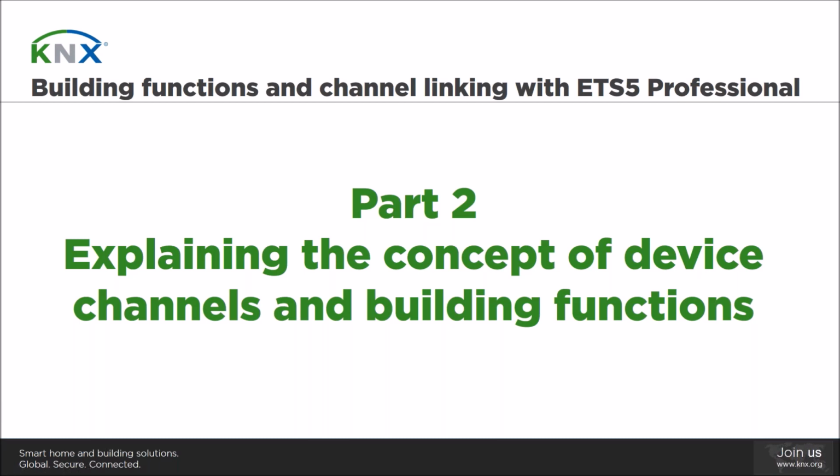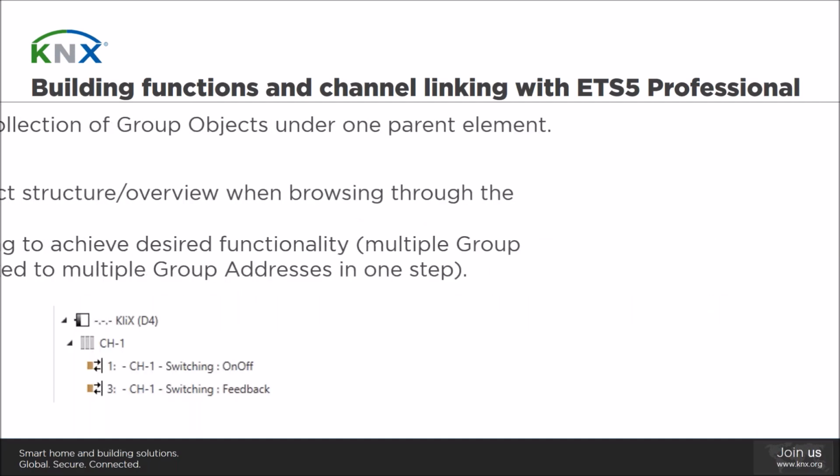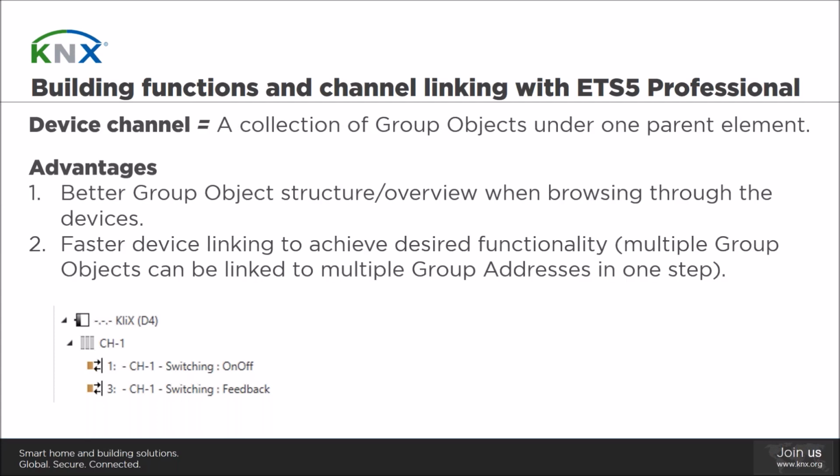Now, let's dive into our actual today's topic, starting from the theoretical part, which contains a short explanation for the channels and the functions within ETS. A device channel shall be seen as a collector of group objects. Some of the benefits of having the group objects grouped into channels are, first of all, you get a better overview of the devices and their respective group objects and consequently their functionality.